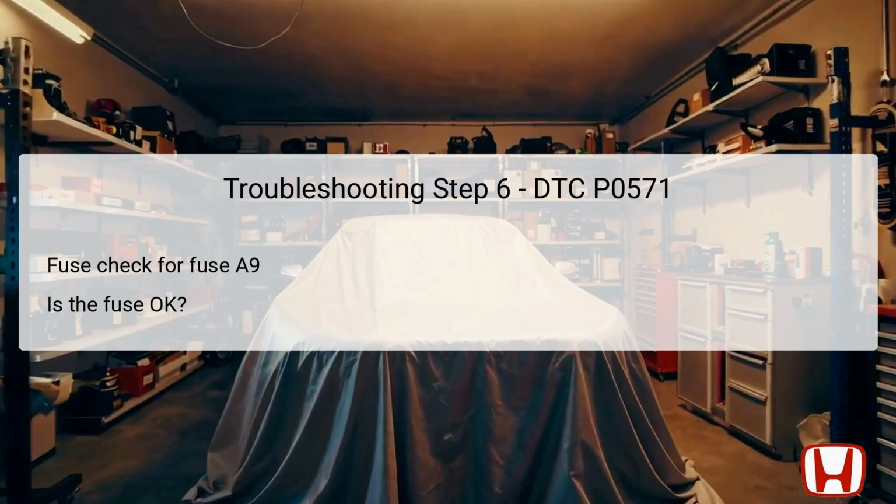If the fuse is found to be blown, it needs to be replaced immediately, and further investigation should be undertaken to identify possible causes of the short circuit that caused the fuse to fail. Alternatively, if the fuse is intact, it suggests that power is being delivered to the switch as it should be. Each check at this stage is fundamental to ensuring that the circuit remains unobstructed and capable of performing its intended functions.